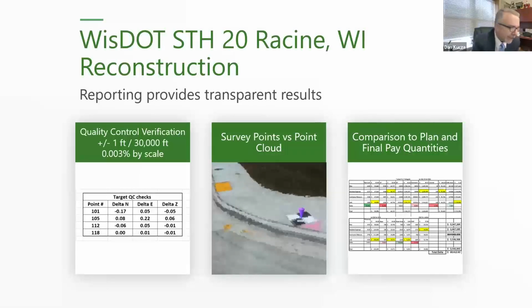Then I went back and shot those same points with a level to verify that. I also measured the coordinates of my digital twin model to look for error. You're seeing there 0.101, about 2 inches off in the northing, which is pretty minimal when you're talking about a $10 million job this long. So we're pretty comfortable that our stuff was to scale.